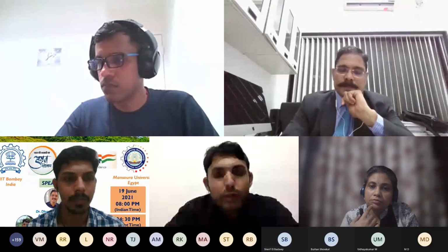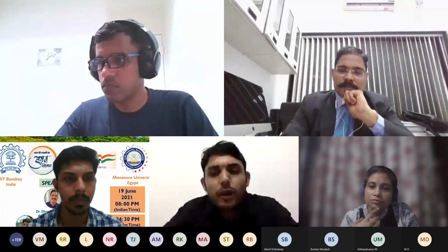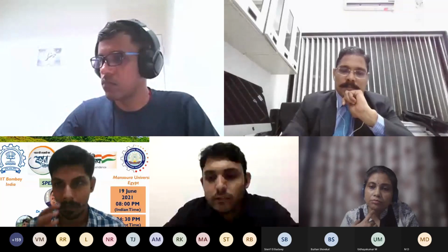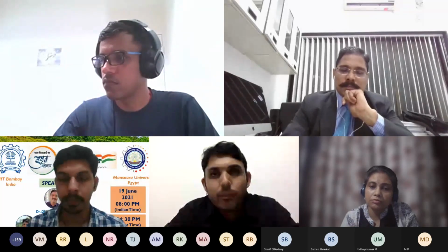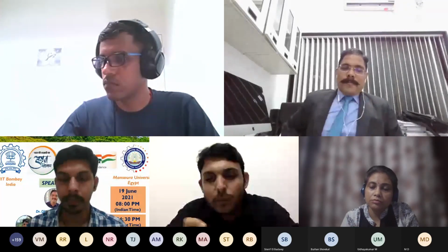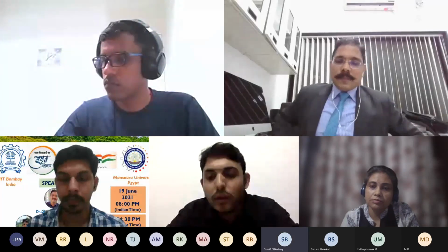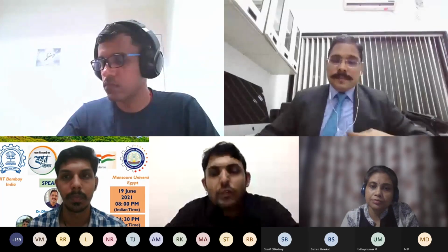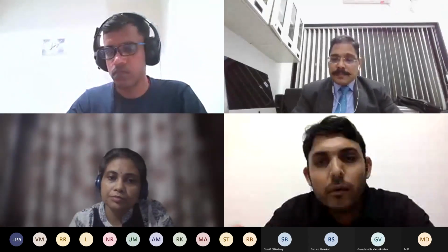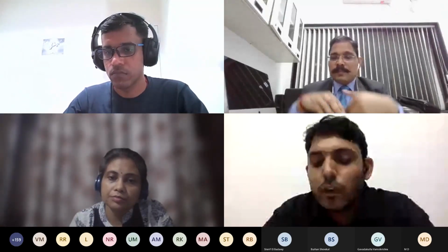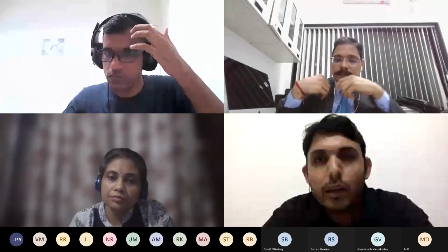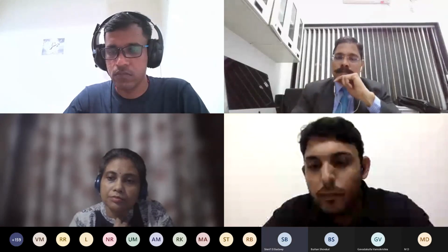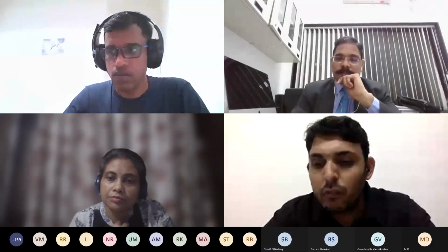There are negative effects, and the major effect is shrinkage cracks. The California department uses typically 2 to 4 MPa in the CTB. What we fear is that if your UCS is higher, shrinkage cracks may develop with time, and that definitely is not good from the pavement structure point of view. So maybe Professor Singh, if you can add.